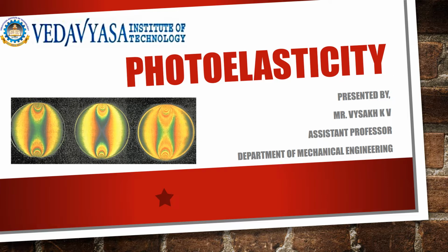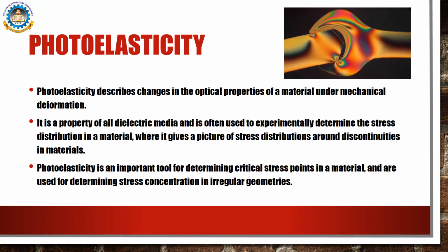Today I am discussing the basic concept of photoelasticity and its application. Photoelasticity describes the change in the optical properties of a material under mechanical deformation. It is a property of all dielectric media and is often used to experimentally determine the stress distribution in a material, where it gives a picture of stress distribution around the discontinuities in materials.